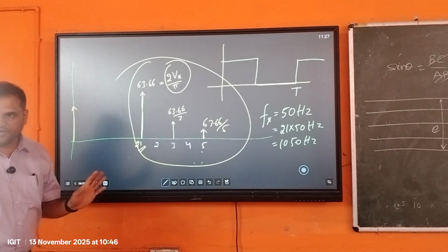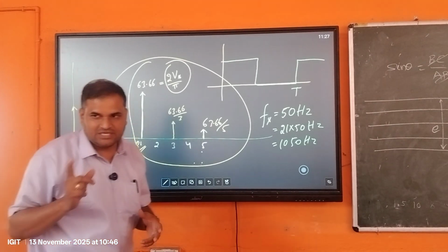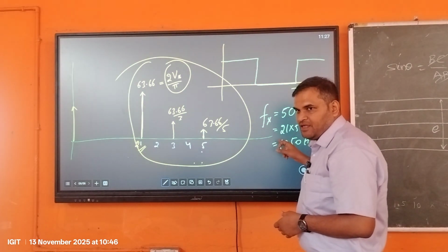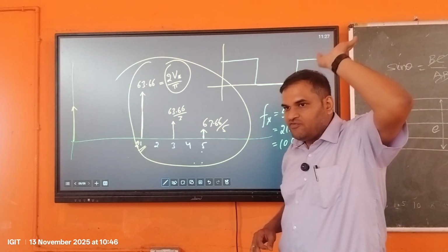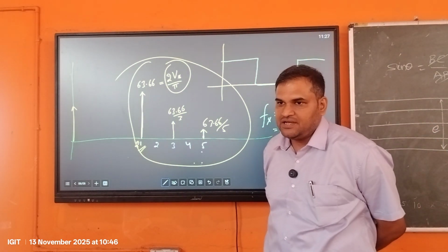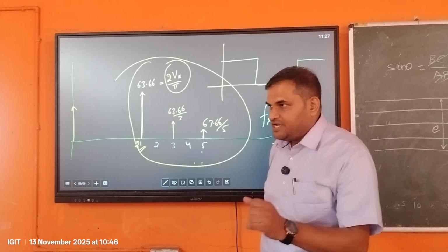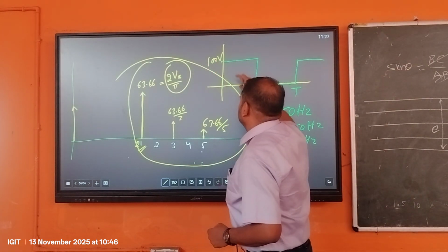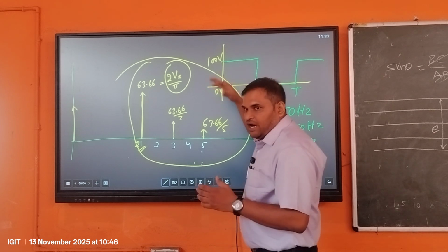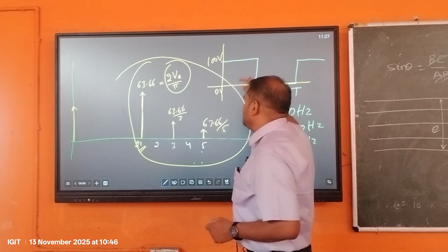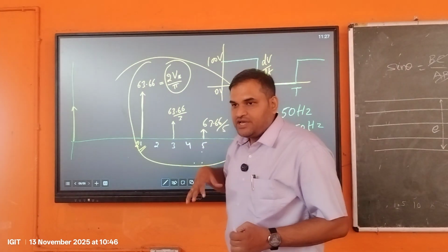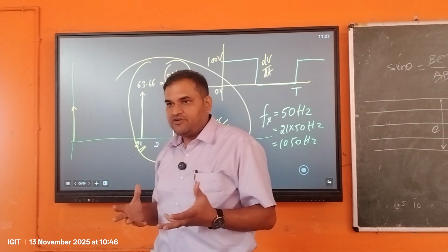So this is okay for a DC-DC converter, and that is the answer to the question why you prefer higher frequency. But somebody will say, okay, we will go for megahertz. What is the answer? If you go for megahertz, remember that when you are switching from 100 volt to 0 volt, there is a rate of change dV by dt. A high rate dV by dt will create an EMI effect, electromagnetic waves.